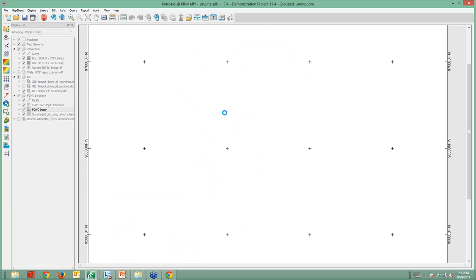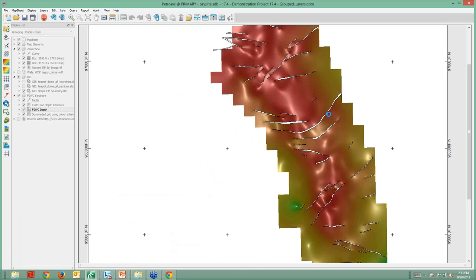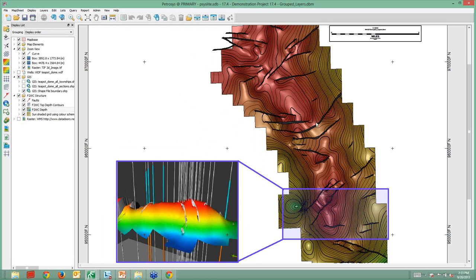But you'll also notice if you zoom in on some faults, the way that we assign top and bottom in the apexes, so how we display fault symbols, has also improved. So if you've noticed issues with that in the past, you should see a lot better handling of fault symbols, making sure fault symbols don't wrap all the way around faults now.